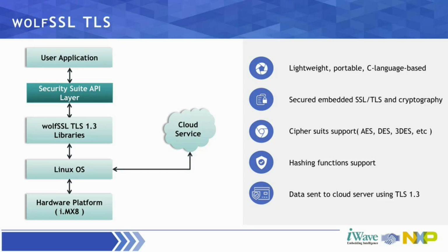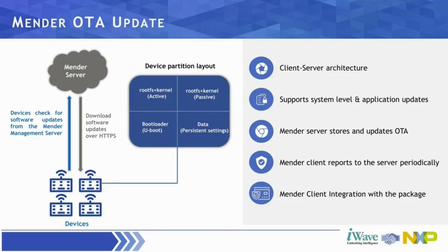Now we're going towards the Mender OTA update. For system level updates, we require a dual A/B rootfs partition on the device. This ensures that the device can recover if the deployment is incomplete or corrupted during installation for any reason. If the boot succeeds, then Mender sets the updated partition to boot permanently when Mender starts as part of the boot process. And when the Mender client downloads and installs the images, other applications on the device continue to run as normal. So the security suite has integrated Mender OTA.